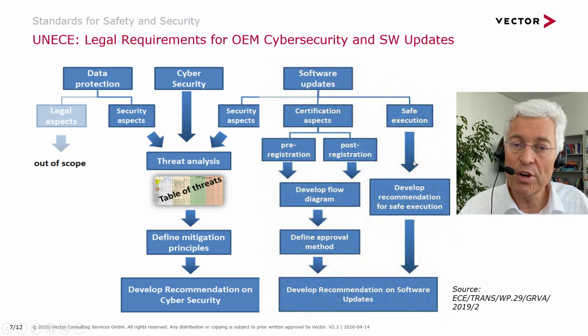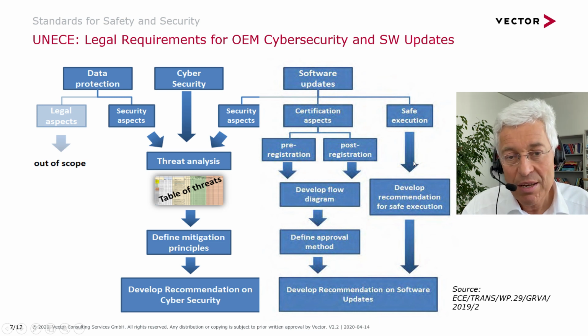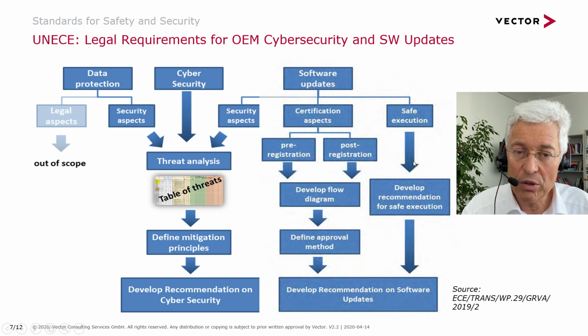Now we do a software upgrade. The software upgrade might impact an ECU, and suddenly the headlight could no longer be dimmed if a vehicle is approaching us. Obviously this is a safety risk, governed by R48. So this software update cannot be delivered, because it's a violation of a type approval parameter.